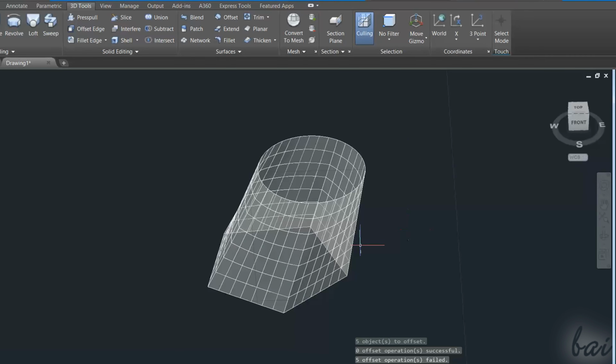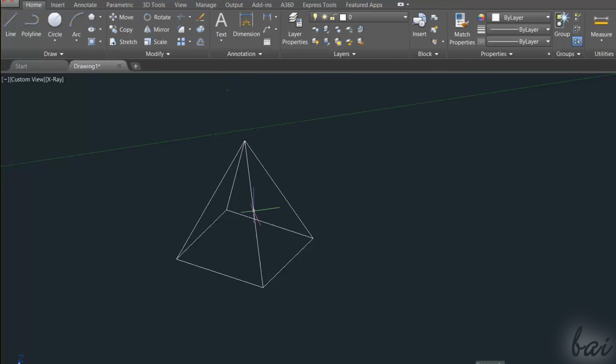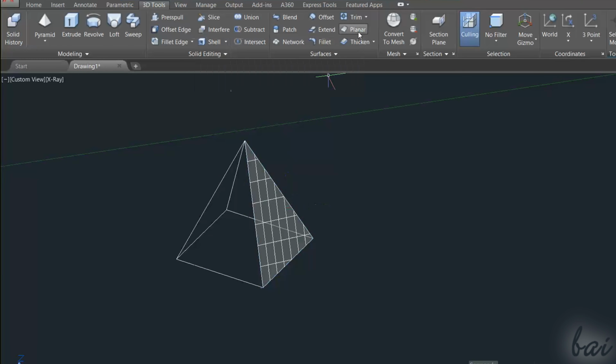You can also extract surfaces from 3D objects. For example, if you use the Explode tool on spheres and tori, you will directly obtain a surface with such shape and no volume. If you have boxes and pyramids, you may need to use the Explode tool once to extract the regions and once more to extract the single sides and vertices. Then, create the surfaces with the Planar Surface tool and group all of them together.